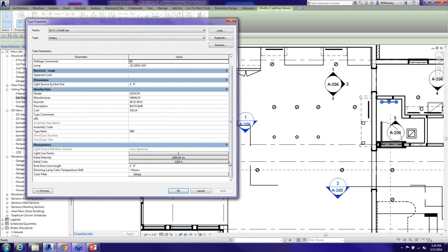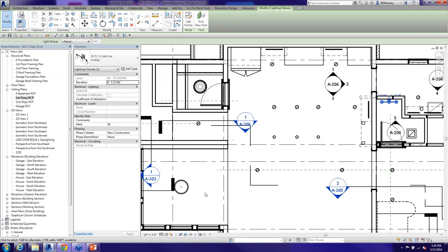Yeah, so if I grab a light source like this one, and there's no IES file, it doesn't give me this little property that was on the other one saying photometric web. The reason I'm talking about this is when they first introduced the new rendering back in, I think, 2009 or 10 with Revit, I kept doing all these renderings, and my can lights would broadcast light, but the can light itself would not light up. I did a camera looking directly into the can light, and it looked completely black.